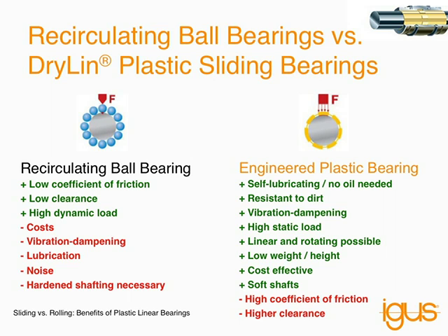This slide highlights the main benefits of each part, which are in green, and the main problems with each part in red. So you see ball bearings, because of their low coefficient of friction, enable applications that are hand powered to be moved easier. They require smaller drive forces. They also enable higher cantilevered loads. Ball bearings are also low clearance. Since they use rolling technology instead of sliding technology, they can be made to smaller tolerances.